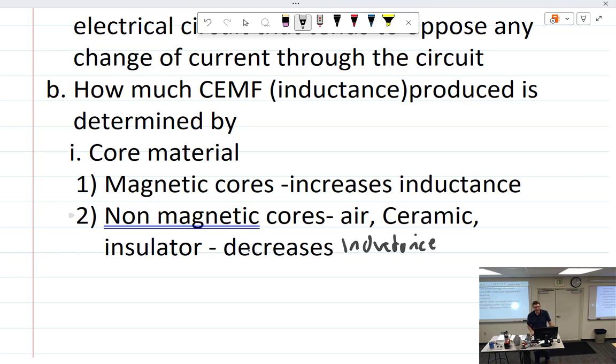The reason is that when we take a coil of wire and create a magnetic field, air is an insulator to a magnetic field. It doesn't like it. It wants to travel through something, just like electrons do. If we use soft iron, which has high permeability, which we'll talk about later, it allows magnetic lines of flux to travel with ease through it.